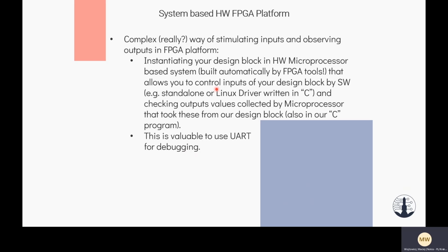So after playing a little bit with FPGA tools, you should be able to get a real multi-peripheral microprocessor-based system in your FPGA with your design included, and controlling can be done like via any microprocessor system, via Linux drivers written in C or standalone drivers written in C. So let's assume you have the transaction layer between hardware and software, and have some Linux embedded system in your FPGA working with this microprocessor. So you can write bash scripts translating to C, or tests directly in C, in which you can control inputs of your design via simple variables, and also read some status and outputs of your design from the level of C code. This can be very interesting.